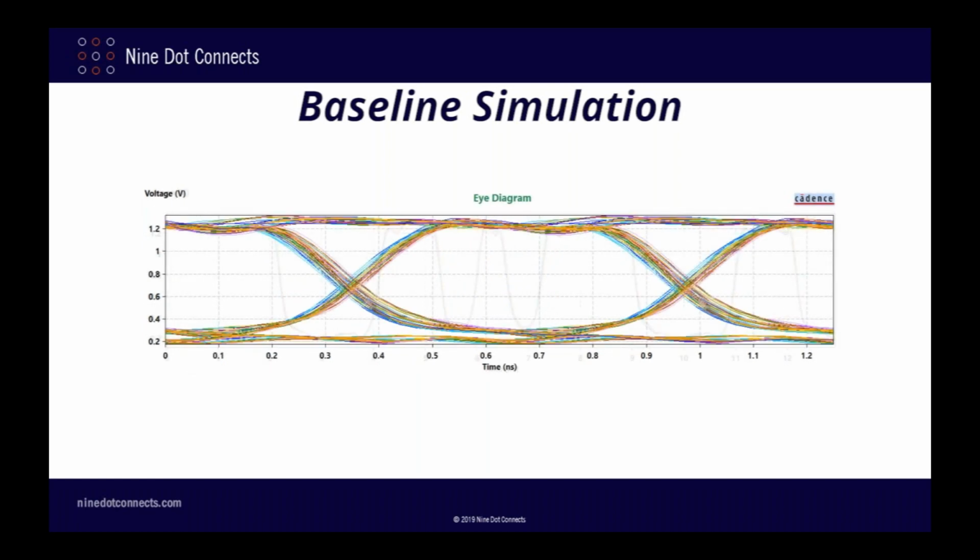So we can use a different kind of waveform called an eye diagram to help us examine things in a different light. Eye diagrams are essentially a convenient means of examining the interrelated timing aspects of many signals at the same time. They are created by overlapping all of these signals of interest, triggered from a common clock edge. And as you see here, the end result is a diagram that has an opening in the middle, somewhat resembling the shape of an eye, hence the name eye diagram.